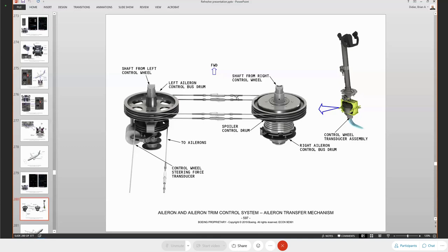You have to remember that on the MAX, the wings are different. They're very skinny out towards the far end. And if I'm in a move or a turn, and I have panels raised up, and I'm in a move that would cause damage to those tips, I'm going to lower the panels probably on one side or the other to relieve that pressure. It's also looking for the same thing on the aft fuselage. If I'm in a maneuver that's going to cause damage to the aft fuselage, we're going to automatically move those. So yes, that's automatic.